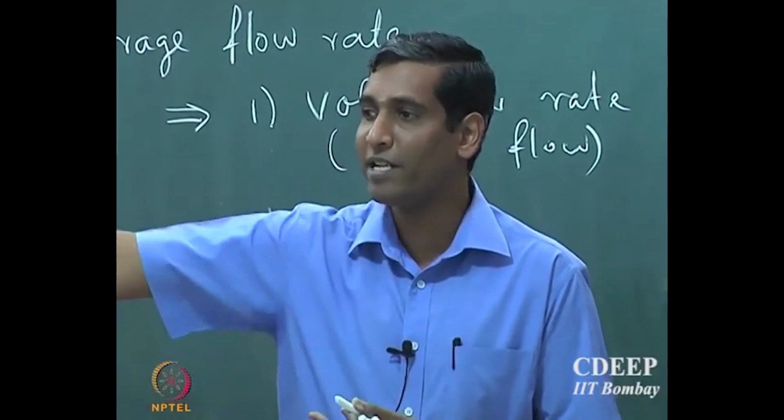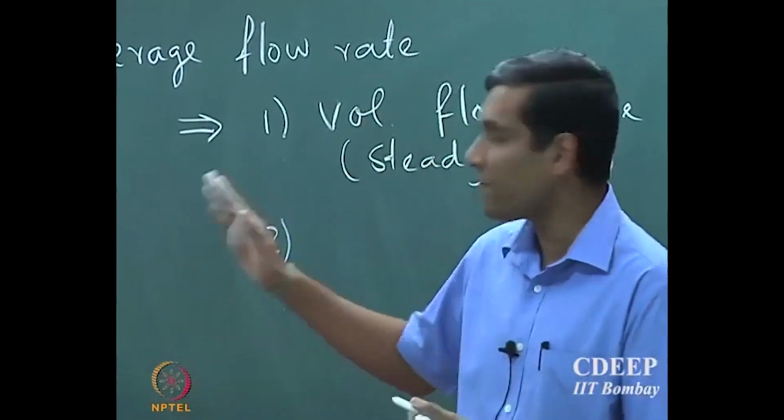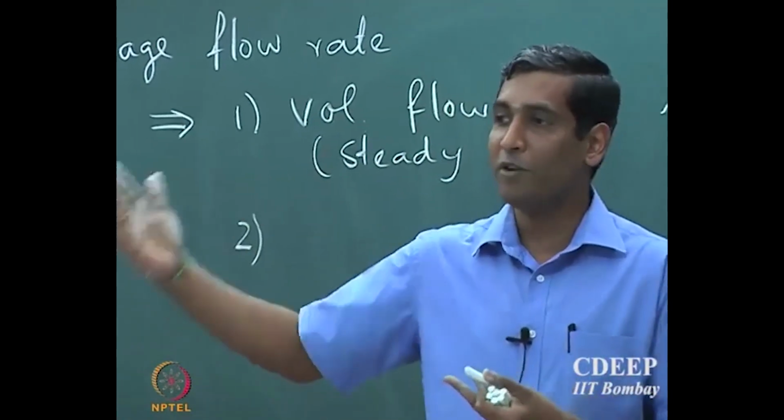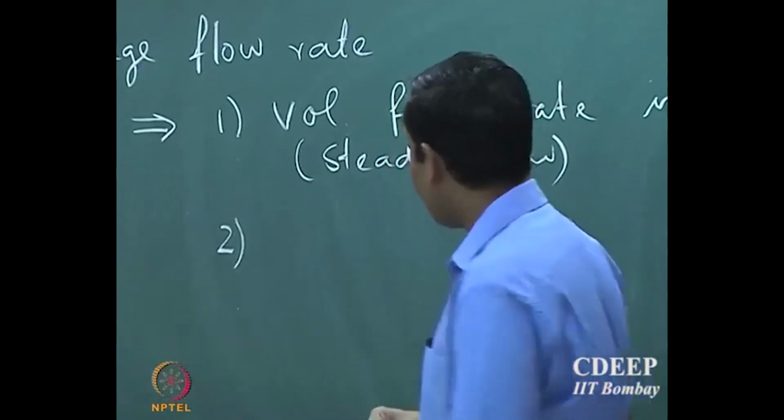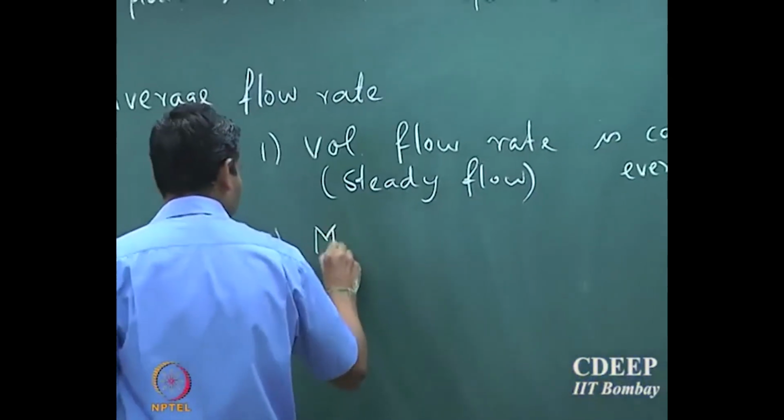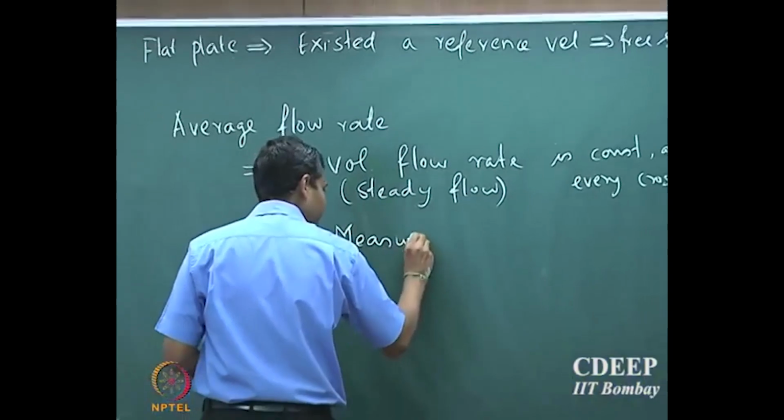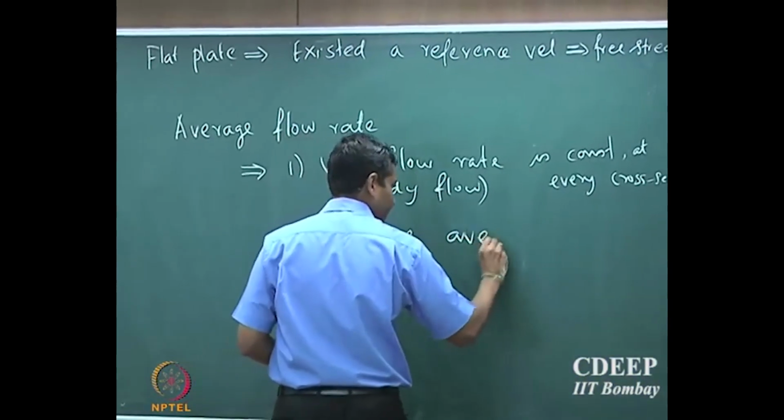Note that the profile doesn't change after the fully developed regime, so you can measure the average flow rate. That's a very important point.